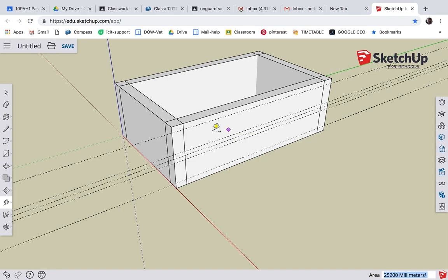We're only going to have 2 dovetails, tail 1, tail 2. So on the top, I'm going to put some angled lines on here. These guidelines, where they intersect this line going down here, are going to be the starting point of all those guidelines. Now the guideline tool is under the tape measure one here, protractor. We're going to click on that.